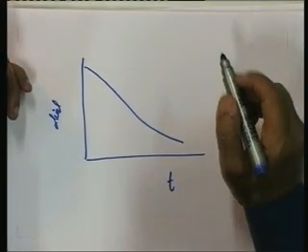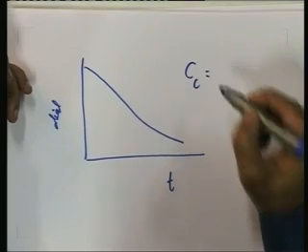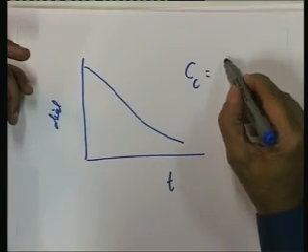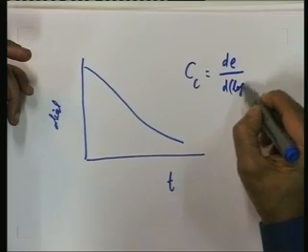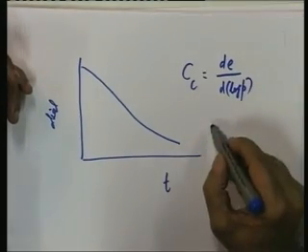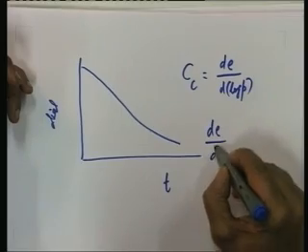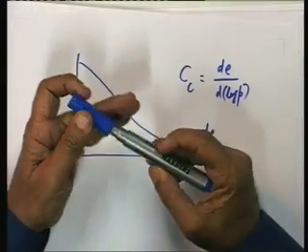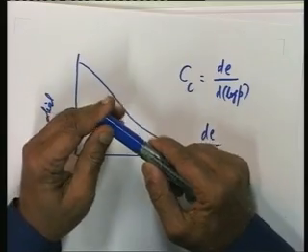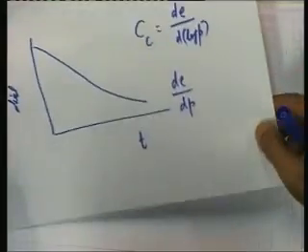because we are finally interested in, for determining Cc, the expression de by d log p, and for determining Av, Mv, we need de by dp. This means that void ratio versus pressure curve is a must. It is unavoidable, it needs to be drawn.